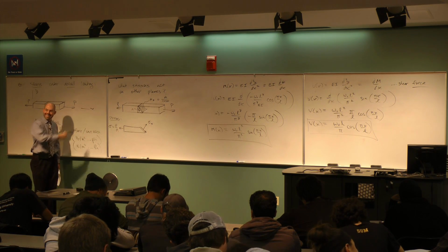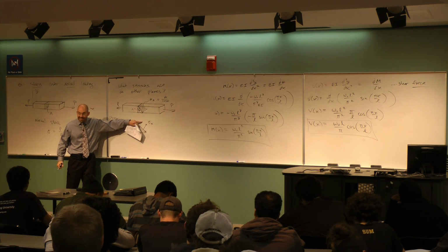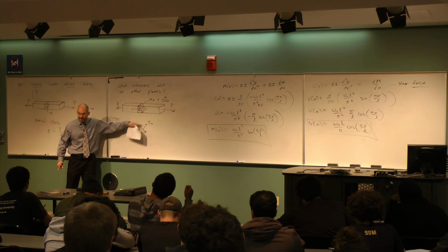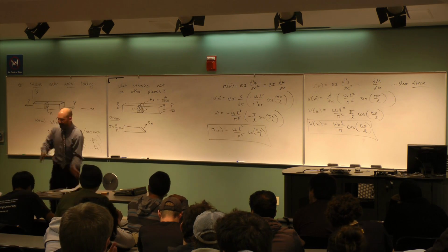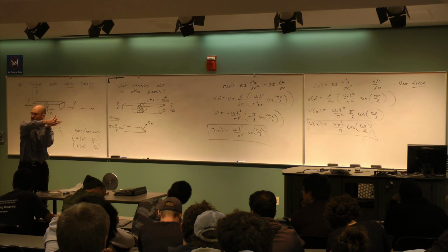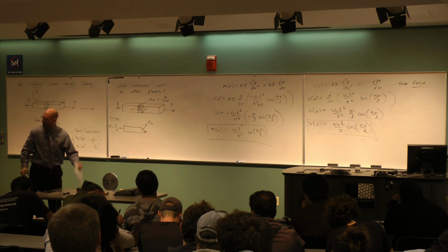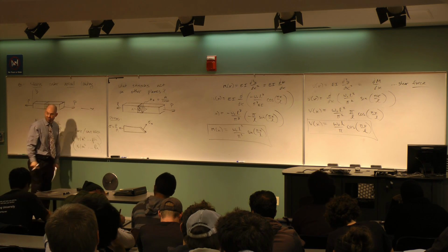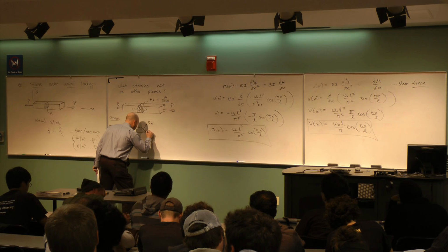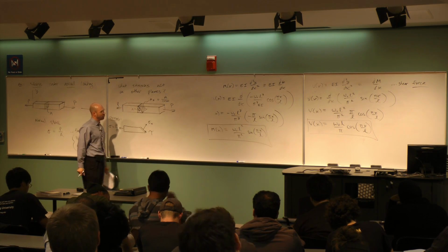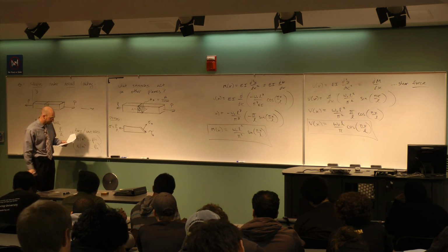So if I look at an angle, key point, normal stress is not the only thing I have. I have to have something that looks like it's sliding, right? I need to have sliding inside the material in terms of a force. A sliding stress is what we call shear stress. Okay, and so what I end up with here is actually shear. We use the Greek letter tau to represent shear stress. I'm calling it tau theta because it's at that angle.